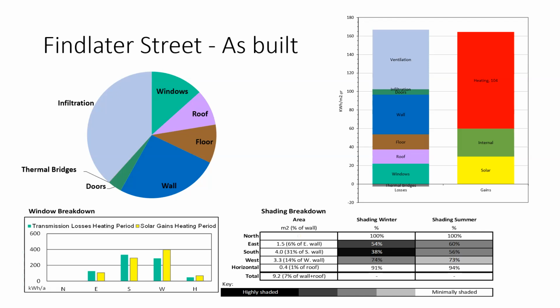So there's only 38% solar gain that would be available actually getting into the windows. So that's having a significant impact on the actual performance. And again, it is dictated in part by the local context and actual horizon elements, but also by the individual climate file or data set that you're using to assess the building.